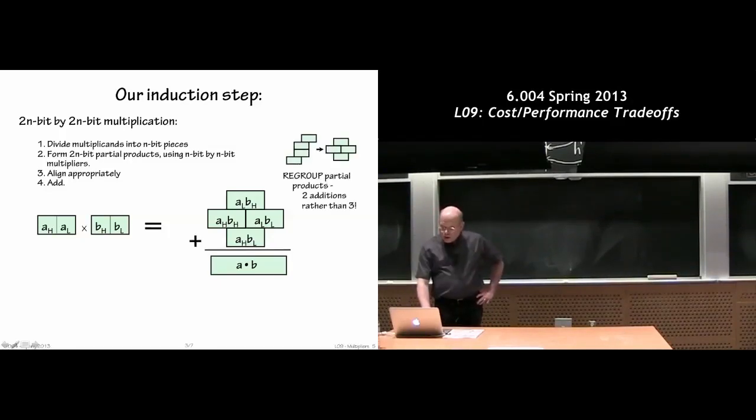And notice what I've done is I've slightly rearranged the order of the partial products. And there's nothing very substantive in the rearrangement. I've just chosen to build something that puts the block in a different order. We still have every bit in the same column it used to be in. We've just organized the bits so the columns are listed in a slightly different order. And there'll be a reason for that, which will become apparent as we look at the next layer of structure.